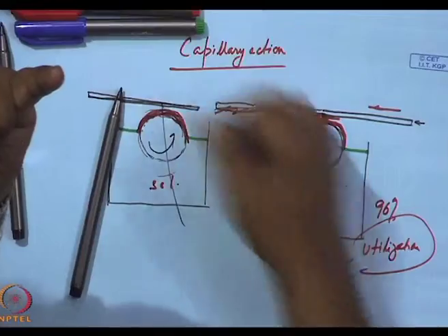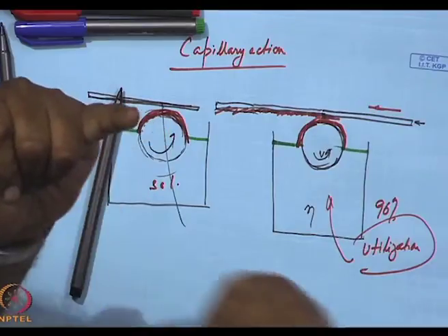In this particular capillary action, where the film layer is formed simply due to the capillary effect and the high surface tension, you have to understand that the evaporation rate will also be very high. And if you go back to my earlier lectures, I had talked of that: when a xerogel, if the evaporation rate is too high, the body shrinks non-uniformly and it will crack.